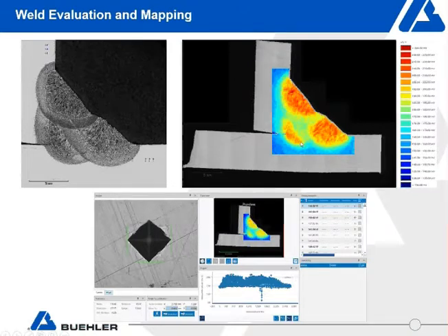But then when you map this out, you do get quantitative data as illustrated in the chart below for different hardness values. And in this case, we did approximately 3,000 indents. This might take a couple of hours to get. So if you're doing weld research, weld analysis, it is a tool to utilize just to make sure that whatever parameters you're using are correct. And the advantage, of course, with weld mapping as well is it gives you a qualitative indication of where potentially you've got high residual stresses due to the thermocycling during welding, and potentially where you'd have failure occurring on that material.